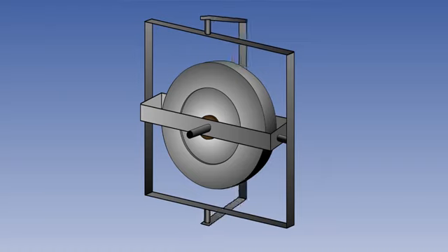This allows the housing, and also of course the aircraft, to move around the outer gimbal. The outer gimbal, or second gimbal, is therefore said to provide 2 degrees of freedom. So, we can see that by mounting the gyro within an inner and outer gimbal system, which in turn is fixed to the aircraft, there is total freedom for the aircraft to move around its gyro without displacing it from its orientation in any of its axes.